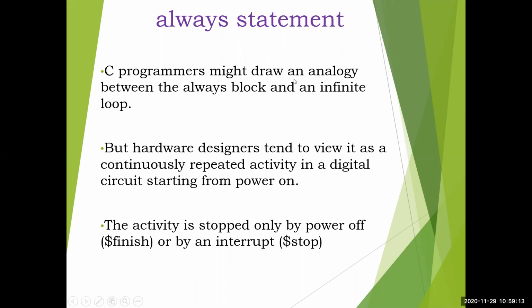C programmers might draw an analogy between the always block and an infinite loop. In C programming, we have the infinite loop concept, like those who are doing embedded system programming. But hardware designers don't use the term infinite loop, they just call it an always block. Maybe the functionality is almost the same, but hardware designers tend to view it as a continuously repeated activity in a digital circuit starting from power on.